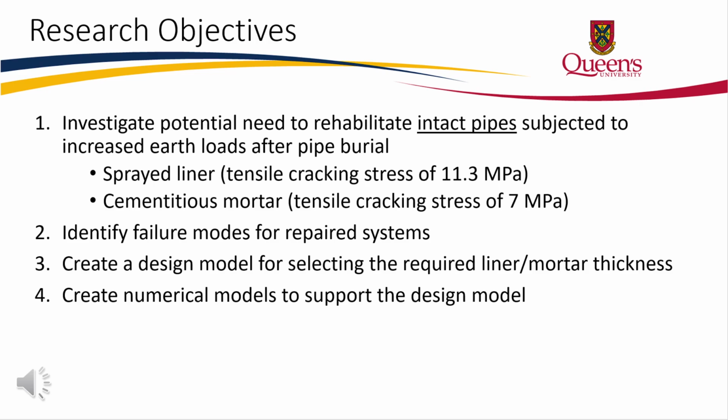So there were 4 research objectives we were hoping to achieve in this project. The first was to investigate the potential need to rehabilitate intact pipes subjected to increased earth loads after pipe burial. More specifically, we were looking to examine how additional load would result in unsafe levels of cracking in intact pipes, and how cementitious liners could be used to return the cracking capacity of the pipe to safe levels to prevent future deterioration. In this study, we look at 2 different cementitious liners, a sprayed liner with a cracking stress of 11.3 megapascals, and a cementitious mortar with a cracking stress of 7 megapascals.